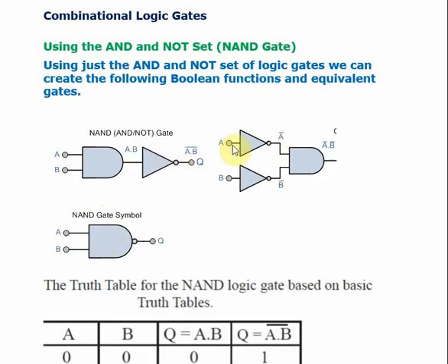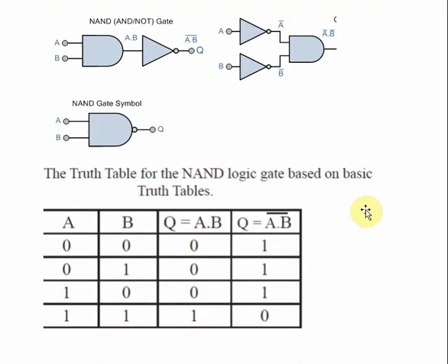Here after feeding the input, we get the output and convert everything using NOT. Here, at feeding time itself, each and every input is NOT. Then we derive the output, right? Now it is very clear, the NAND gate is always opposite to the AND gate. Now compare the output here. This is the AND gate output. We know both switches need to be on to get 1. So NAND is AND and NOT, so here it is the opposite.